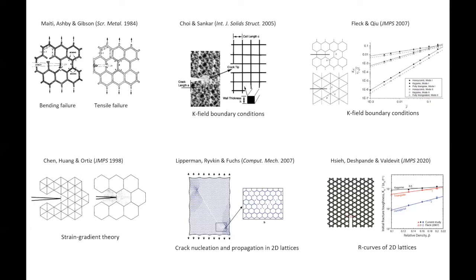local type of failure and propagation. It's really nice. And this work has gotten kind of a bad rep, only because there is some wrong scaling somewhere there. But the strength field theory is, one would argue, the most reasonable thing to use here, because you obviously have different length scales in play. So again, in all of those problems, you assume something, you borrow something from linear elasticity, all right? Whether it is for an orthotropic material or for an isotropic material, you assume that if you have a very long crack and a somewhat infinite domain, those things should be okay.